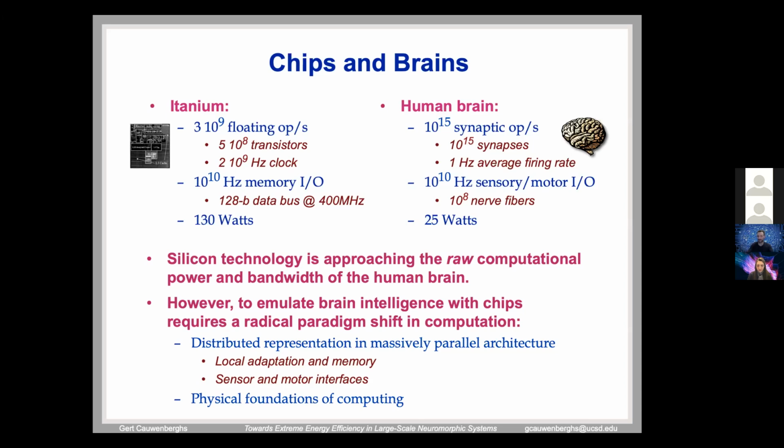And so in every cycle, that charge is delivered from V_DD, from your power supply. And at the end of the cycle, it gets returned to ground, right? You're basically draining it. So in the process, you have moved C times V_DD of charge from V_DD to 0. So the entire energy that you have consumed in one cycle of going up and down with the clock is basically the product of the two, voltage times charge, which is V_DD times C times V_DD. So that gives you C times V_DD squared. Again, C is capacitance, V_DD squared is the supply voltage squared. So that's the energy that you consume for every operation.